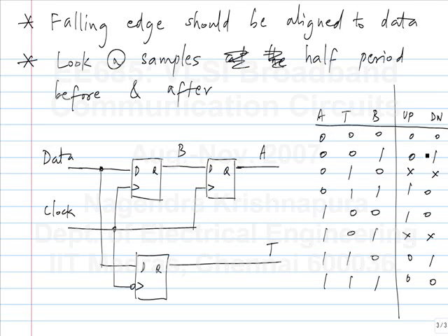And down is? Down is this. Both the don't care cases will become 1, 1. That may be okay in practice. So if you do it with this, you realize it with only 2 gates.